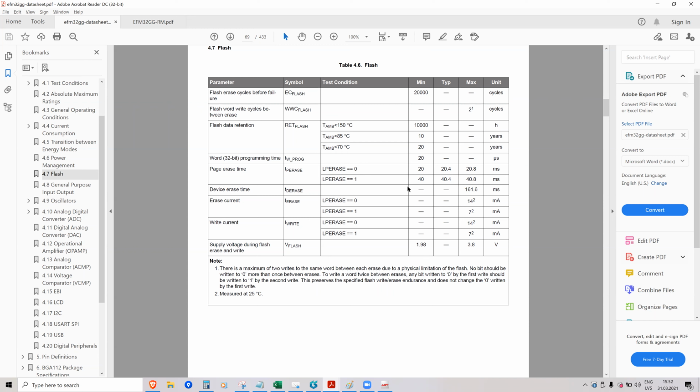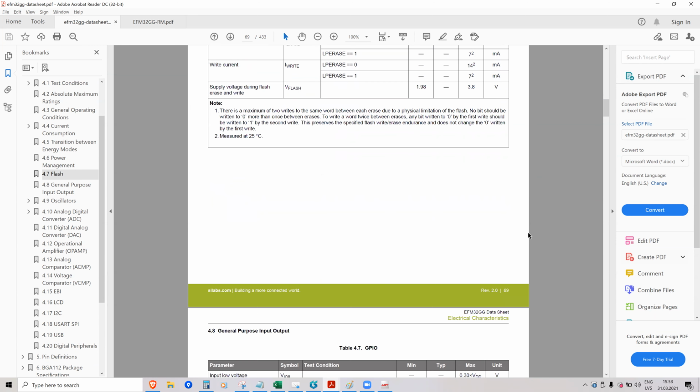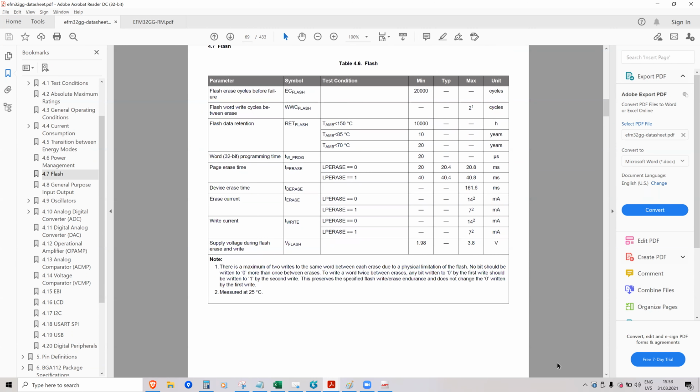And even if somebody unplugs the device, until the capacitors discharge, it will have enough time to reprogram itself. And if the voltage is lower, it indicates that somebody has already switched off the power and they're discharging slowly, and you should not perform this firmware upgrade, for example. And you have all kinds of currents here. So when you design your device, just take this into account.